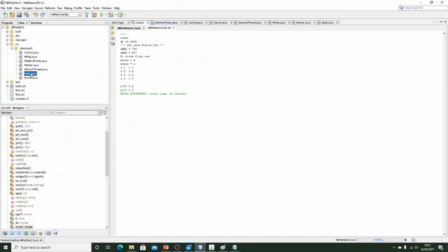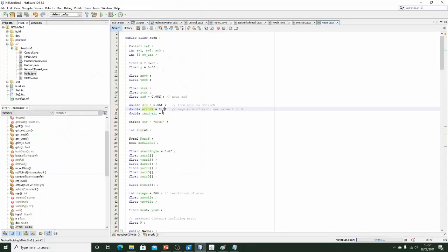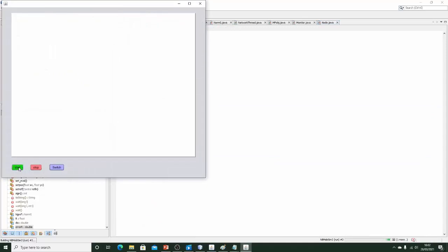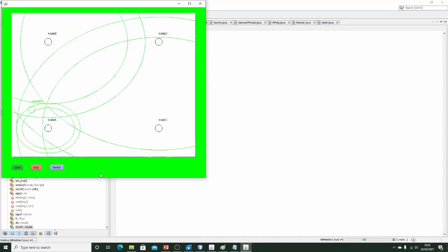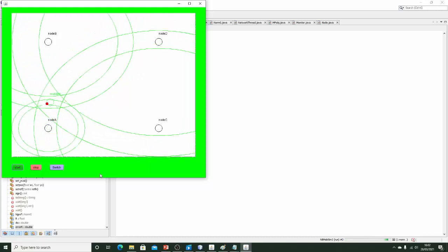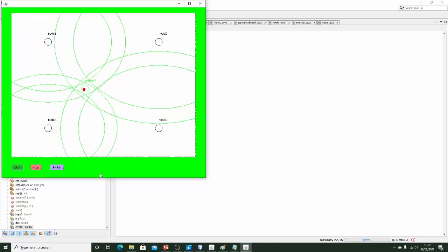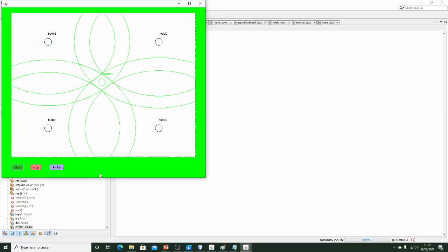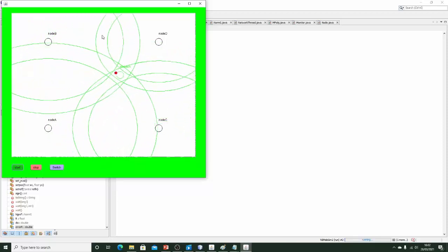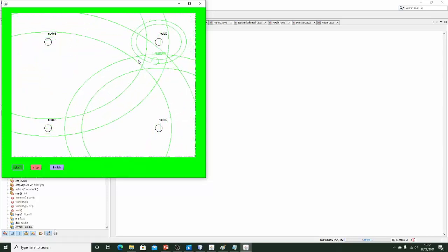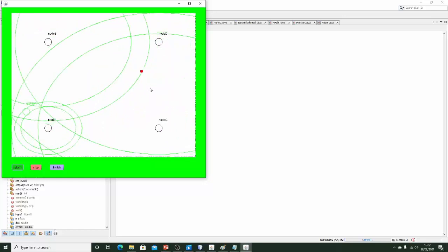What I'll do now is change the error measure to something quite large, say 10, which is much larger than a real typical situation. And I'll switch on the error bounds. The error is a percentage of the distance, so you'll notice that as this gets closer to this node, the absolute error size diminishes, while at the same time this one is getting bigger.